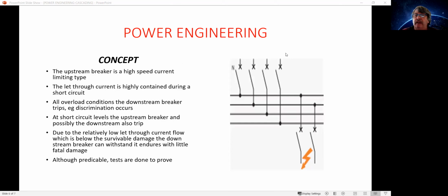If you're talking about any breaker really at the top end of its performance, we must understand that breaker has a very limited life. Whereas a fuse goes bang once, a breaker may only go a handful of operations, possibly 2 or 3 operations, and then a replacement is needed.